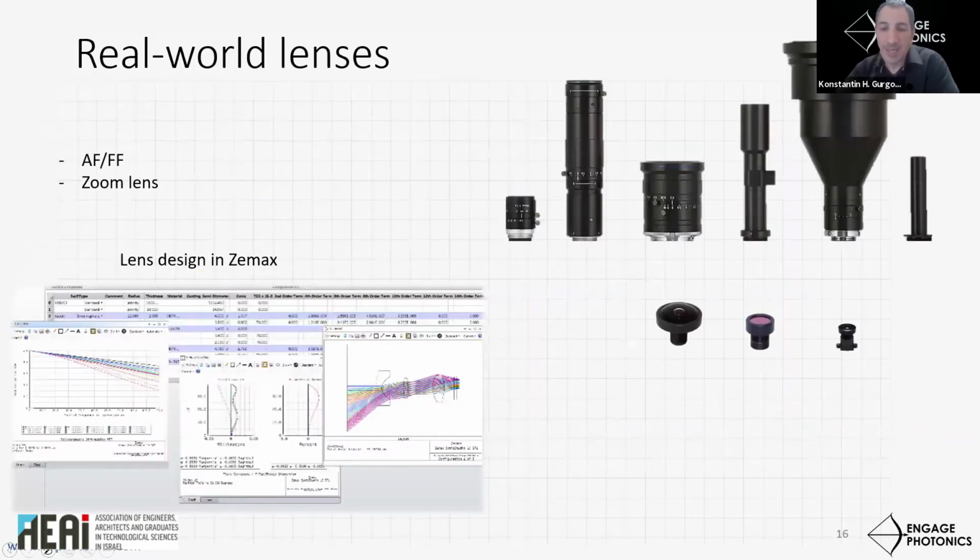So what the lens designer does is combine different lens materials and shapes and make them compensate each other for aberrations, so that eventually the light rays behave well and give a sharp image. If, for example, you add an optical filter between the lens and the image sensor, it will sometimes break that balance and image quality will be degraded.